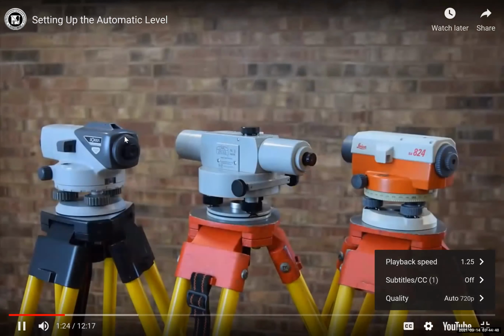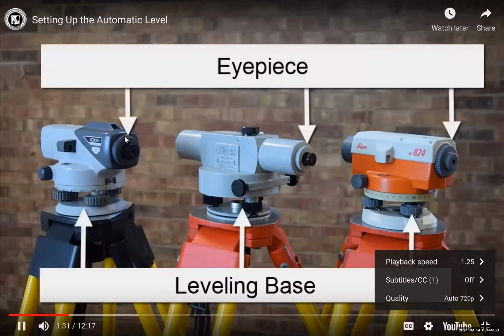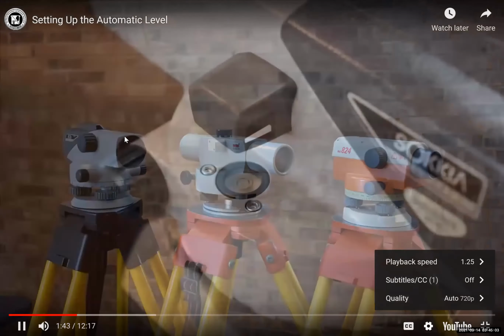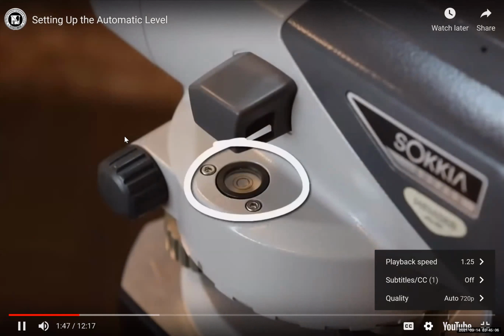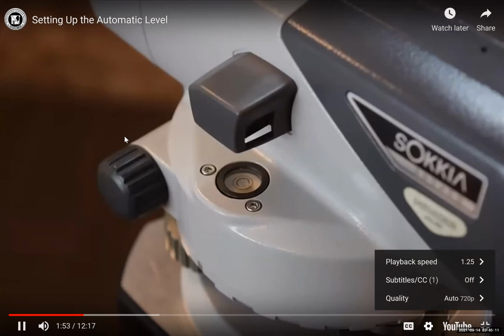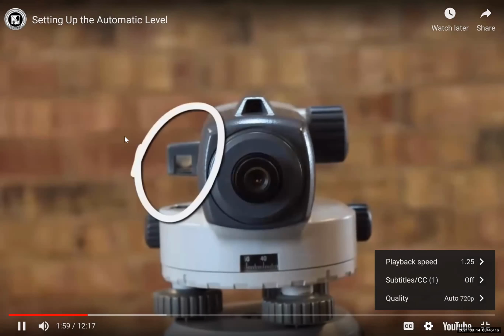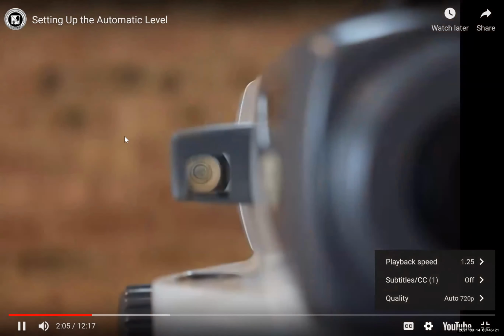In this view, you can see that each telescope has a telescope eyepiece and a leveling base. The simplest and most reliable modern instruments use 3 leveling screws. Here you can see the objective lens and the objective focus knob. Each instrument has a circular bubble level. When the telescope is properly leveled, the telescope line of sight is perpendicular to the direction of gravity. Some instruments include a small mirror that enables viewing the bubble level from the end of the instrument, like you see here. This convenient feature speeds up the setup process.